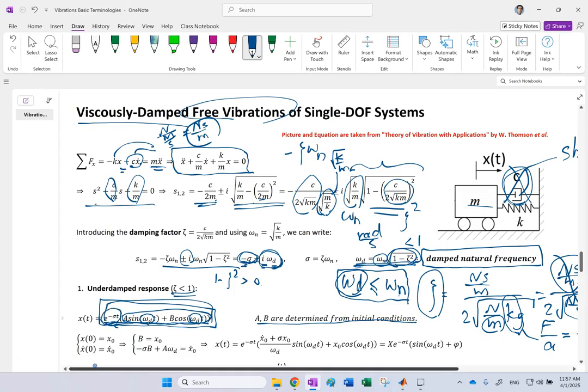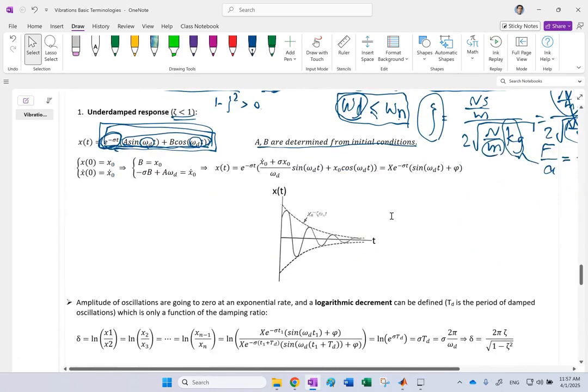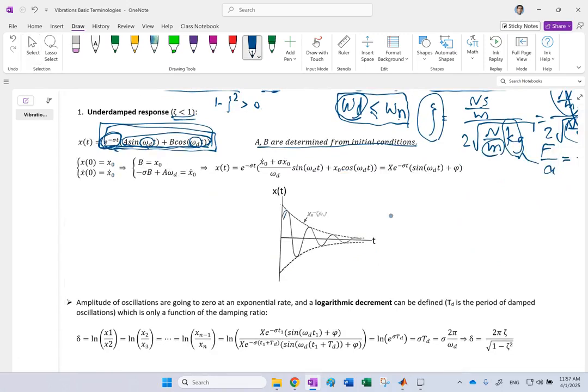If the amplitude is initially square root a squared plus b squared, over time it is going to go down. So the behavior that you would get out of the system is a damped harmonic. So you see here, this is a harmonic, and the frequency of this is omega d, but if you look at the amplitude, it shrinks over time. Ultimately, it gets to what? It gets to 0.